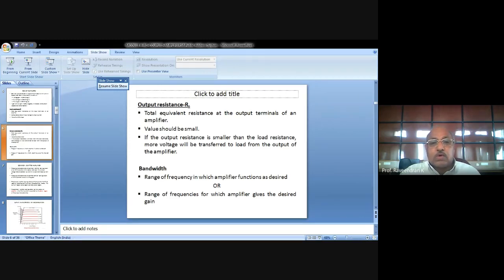Okay, this is just for giving you an understanding of voltage divider biasing. We will come across the real operation of the RC coupled amplifier now. The operating point can be made almost independent of beta. I told you why the operating point must be independent of beta, that I have already explained to you earlier.